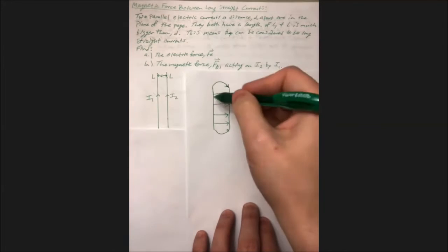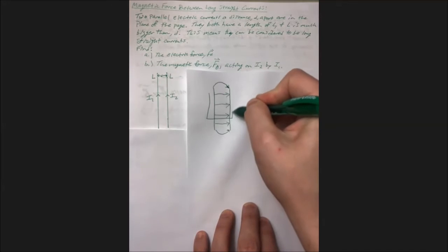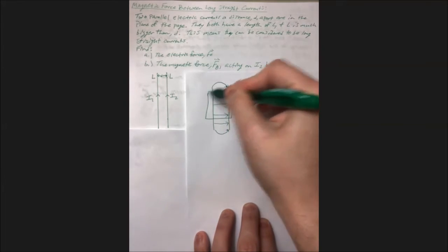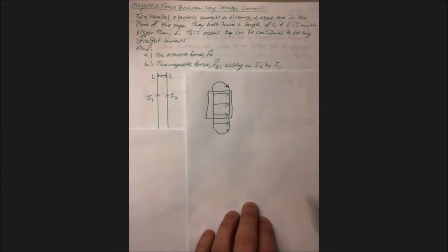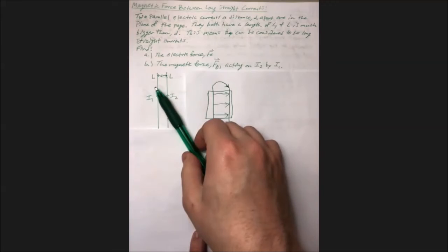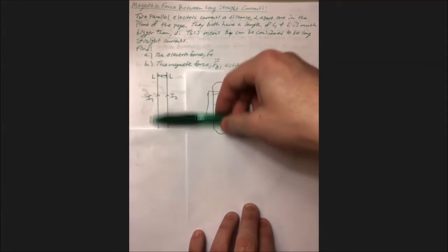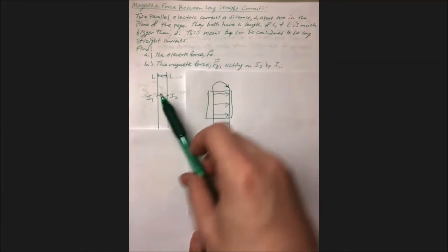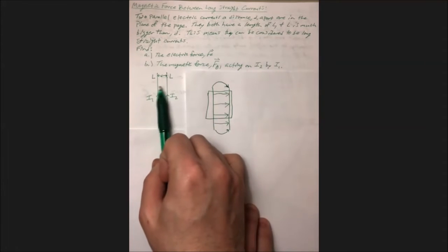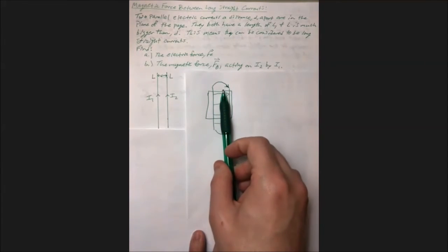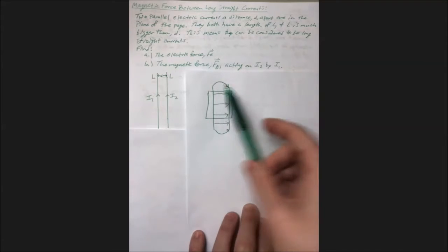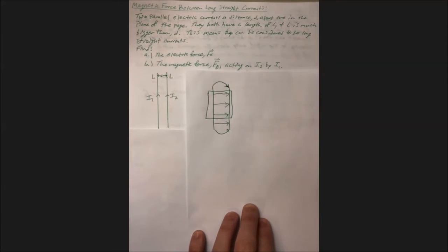And so we would always only look at the middle section of the parallel plates so that we could avoid taking into account any fringing. That's the same thing that we're talking about over here. We're going to say that it's so long compared to the distance between them that we won't have any of this fringing effect to take into account.